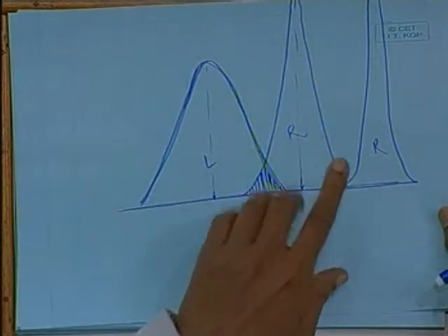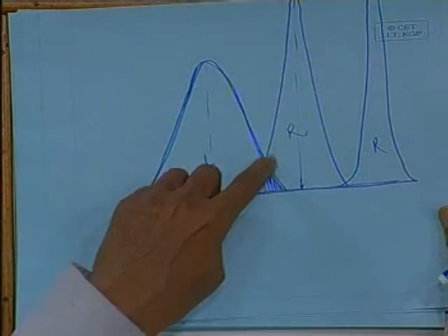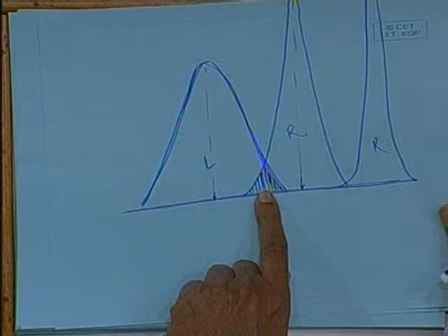The level 3 reliability is extremely difficult, mainly because we do not know the nature of these curves. Even if we know the nature of the mid portion of the curve, we do not know the nature of the ends of the curve, which is where you are actually doing the integration to find out the failure mode.